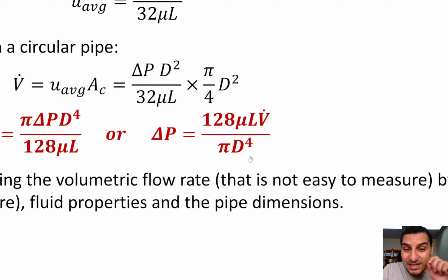It's 2 to the power 4. It's 16 times. If it's 1 atmosphere pressure drop, it will jump to 16 atmospheres of pressure drop, which is a huge increase in the pressure drop. So the pressure drop is highly sensitive to the diameter. And this makes one very, very famous engineering task that we always see in all the pipeline designs, which is how can we choose the proper diameter.